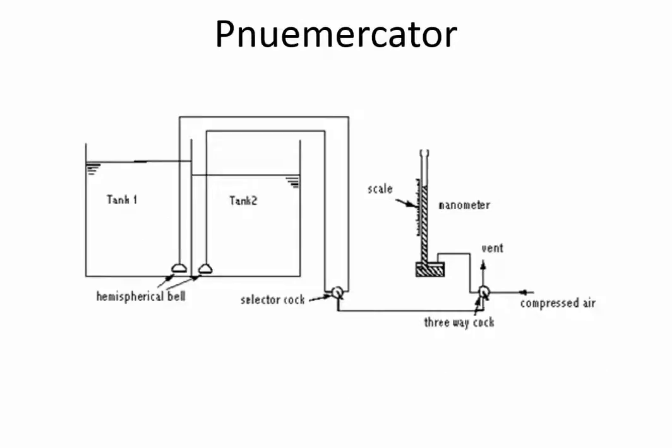And then lastly, there's the Pneumicator. That's the one you saw on the Bluefin. It's a pretty old school sort of system now, but basically it's relying on the level that's in the tank exerting pressure on this pipe, and once we line up the right valves, this will give an indicator with a scale that's calibrated according to the pressure that's exerted by the fuel on this pipe work.